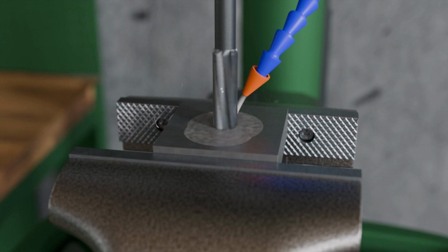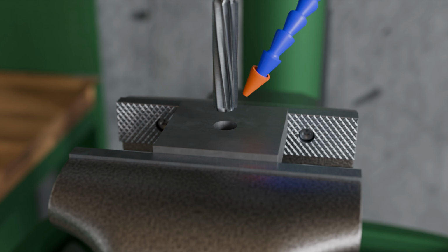Reamers are much more precise than twist drills and are specially designed for a specific nominal size and tolerance grade, in our case for the nominal size 20 mm with tolerance grade H7. Nevertheless, it must be checked afterwards whether the required dimensional tolerance has actually been met, because the reamer, like any tool, is subject to wear and this can cause dimensional deviations. An unsteady run of the drilling machine or incorrect clamping of the reamer as well as the use of an unsuitable cutting fluid or insufficient cutting fluid pressure can compromise the dimensional accuracy.